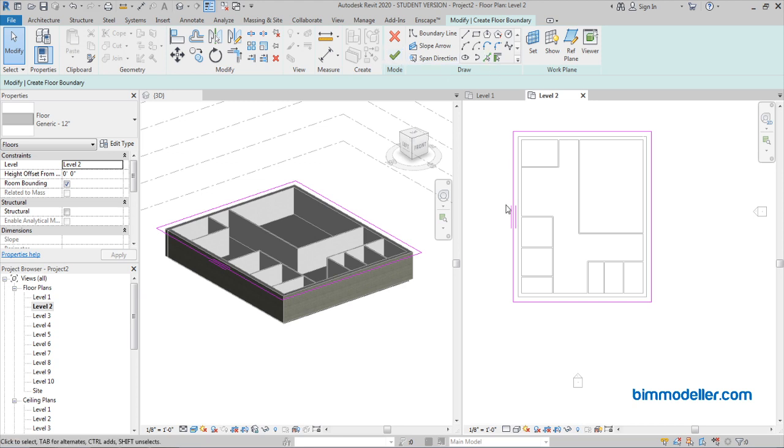After clicking these lines, you have to tap this so that it will detect all the surrounding walls like this. I'm pressing the tab button continuously one by one, so it will detect the possible options. When it highlights all four sides of the wall, you have to click the left mouse button and finish those.